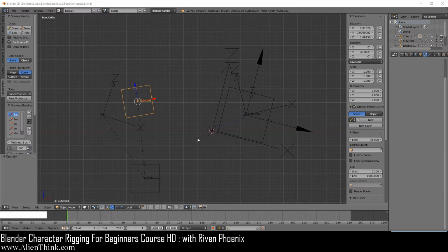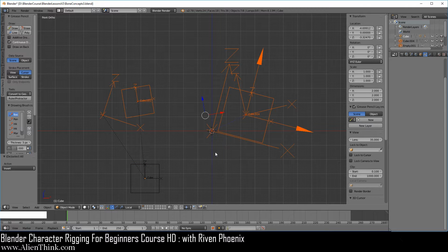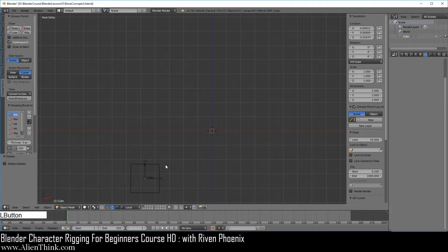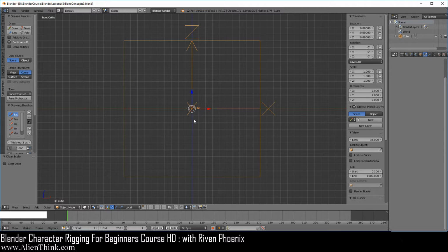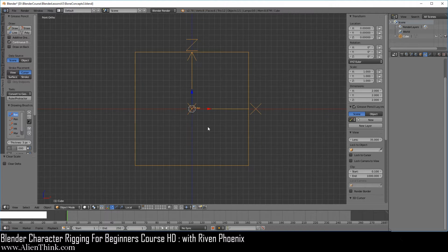So here I'm just going to zoom out and click on this object. I'm only clicking on this object because it just says cube. Now do Control I to invert the selection, do X and delete. Click on this object, do Alt R G S, do Shift Z to place the 3D cursor in the center. I'll go ahead and zoom out a bit.